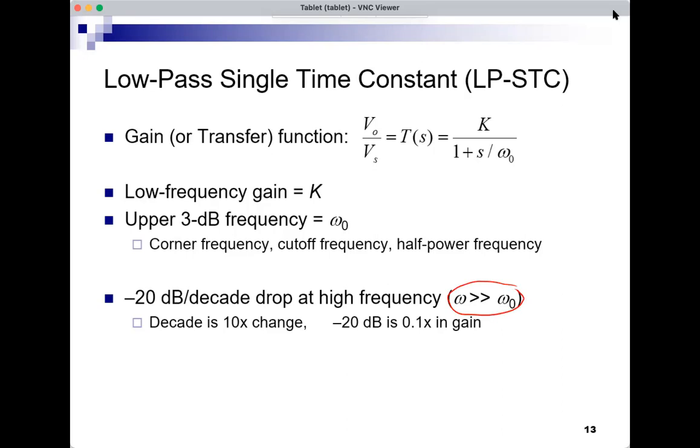So that's pretty dramatic, right? I mean, the gain was 100, and at 5 million, it drops already to 80. And then at 50 million, whoa, it's 8. So this amplifier that had a gain of 100, and it was very nice gain, very good amplification. If the frequency is 50 million radians per second, then this gain of 100 is now 8. If the frequency increases to 500 million, the gain drops below 1.